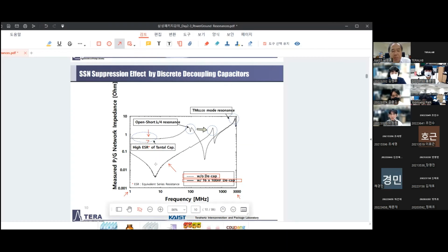By having decoupling capacitors, we were able to reduce the impedance by this amount, and this slope is the capacitive curve. We put 16 of them, but it still has self-inductance, because each decoupling capacitor may have nanohenry inductance, but we can divide by 16.